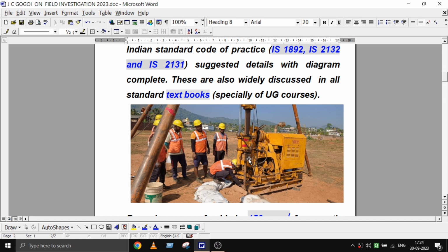The rate of penetration shall be lower as far as practicable, because of the bore water, which means boring fluid, prepared using 5% bentonite to stabilize the hole, unless we are able to provide casing. Initially we have to make the bore, and later the casing shall be separately rotated and penetrated gradually.